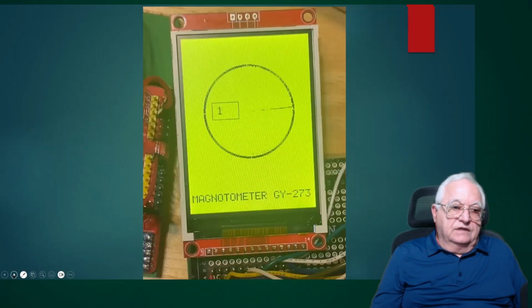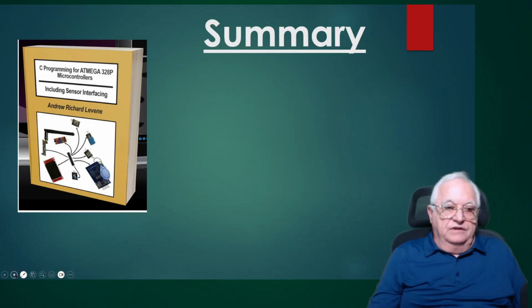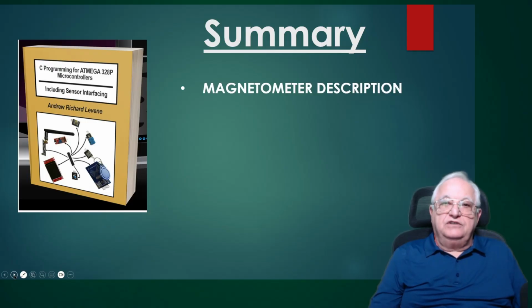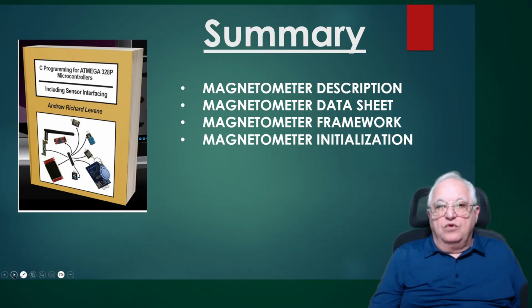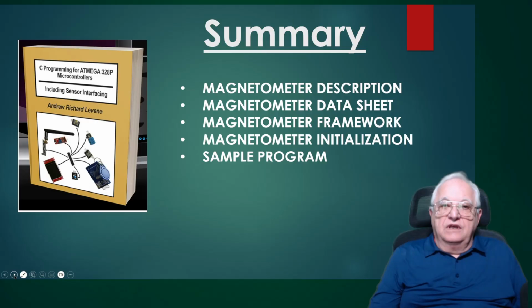Okay, so now what's left is the summary. Today in the presentation, I gave you a description of the magnetometer. Next, we looked at the data sheet. After, from the data sheet, we developed our framework. And then I showed you how to initialize the magnetometer, and we went through a sample program.